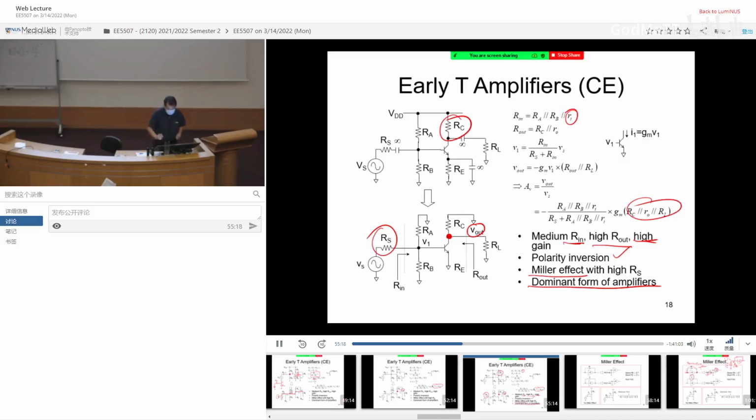So what they do is, I have this amplifier, just terminate this with 50 ohm. Okay, it's a very simple design. So people do use that if they don't care about the noise. Why? Because with a 50 ohm fixed resistance, you guarantee wide band matching. No matter what, it's always matched. And those people scratching their heads using an inductor to match or using a transistor to match, they can reduce the noise, but they are dealing with something else. Inaccuracy in matching. They might not be able to get 50 ohm. Okay?